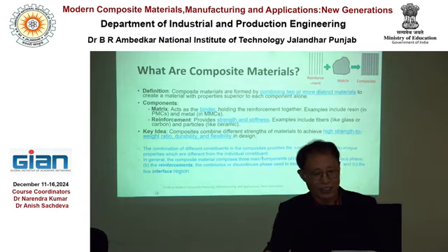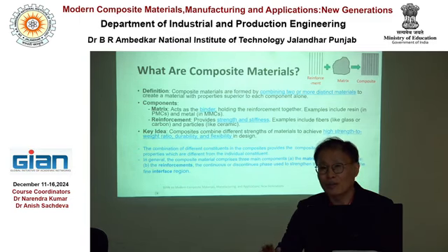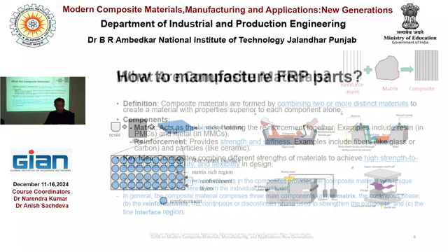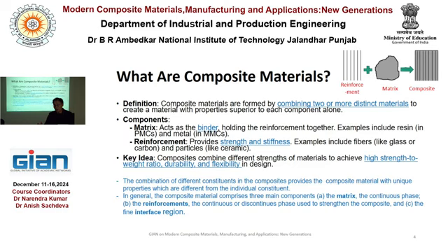And so, although I said the composite consists of reinforcement and matrix, to evaluate the basic property of a composite, there is one more characteristic that must be focused on. It is the interface region, because between matrix and fiber, that zone is the interface. Most of the time the interface characteristic holds the life of that material.